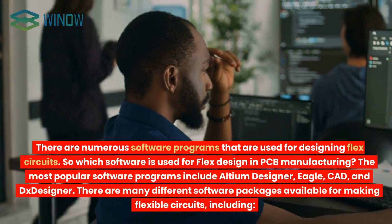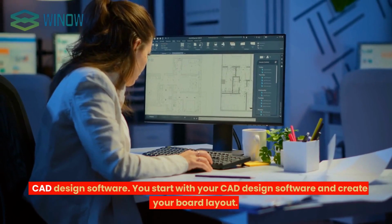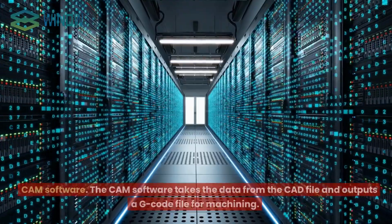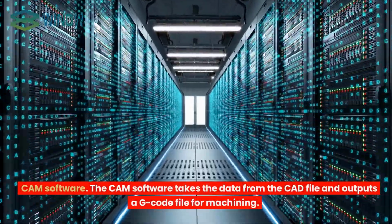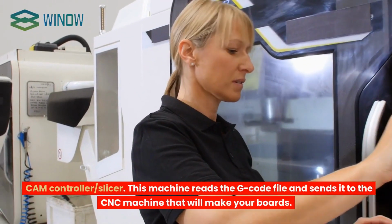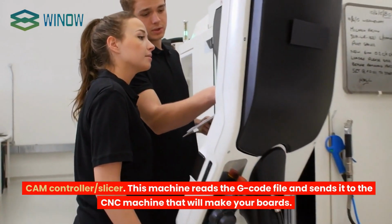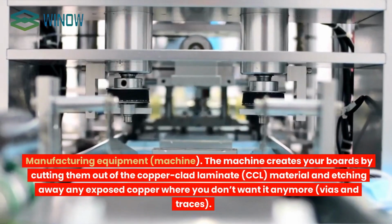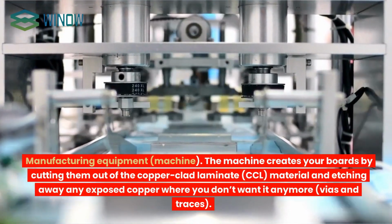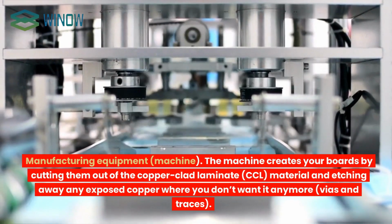There are many different software packages available for making flexible circuits, including CAD design software. You start with your CAD design software and create your board layout. CAM software. The CAM software takes the data from the CAD file and outputs a G-code file for machining. CAM controller/slicer. This machine reads the G-code file and sends it to the CNC machine that will make your boards. Manufacturing equipment, machine. The machine creates your boards by cutting them out of the copper-clad laminate, CCL, material and etching away any exposed copper where you don't want it anymore, vias and traces.